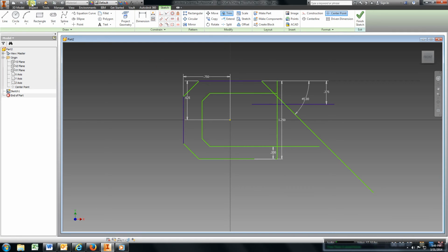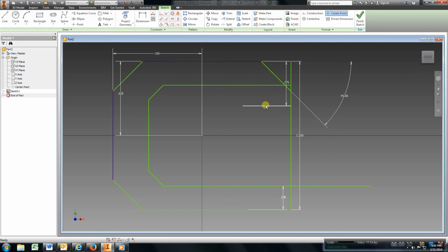Oh, let me go back. Let me hit that back button. That line is going to come down, drop down to this point, come down here. So I'm going to try to trim off this line where it comes down. Trim that one, trim that one. Now hopefully, nope, let me go back. Sometimes you've got to mess around with this a while. I know this line here is going to be 0.5, so I'm going to type that in, 0.5, enter.